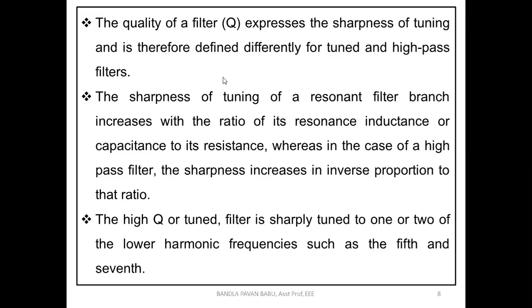Based upon the switching operation performed, we can vary the frequency, which leads to variation in the reactance. Obviously, if the reactance is varied, the impedance is going to be varied. If you are varying the impedance, that operation I can call tuning. It depends upon the harmonic component, what is the frequency of that particular harmonic, whether it is 25 hertz or 25 kilohertz or 100 kilohertz, that's up to the harmonic frequency.